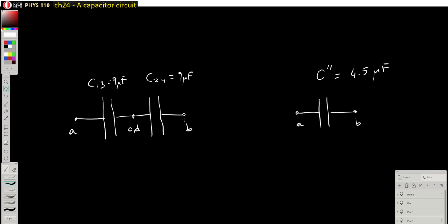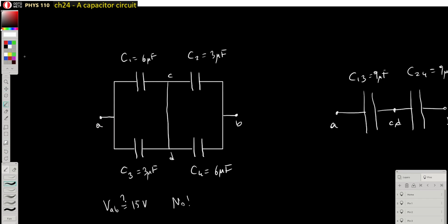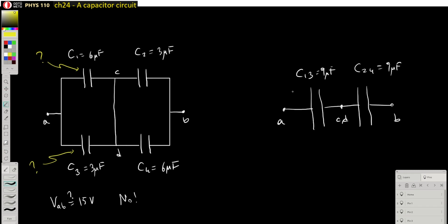Okay, let's come back to the original discussion. I don't know how much charge is in here, and I don't know how much charge is in here. But when I consider these two capacitors as parallel capacitors and consider the equivalent capacitor, the total charge on that plate must be 60 microcoulombs. Minus 60 is on that plate, therefore 60 microcoulombs is on that one too.